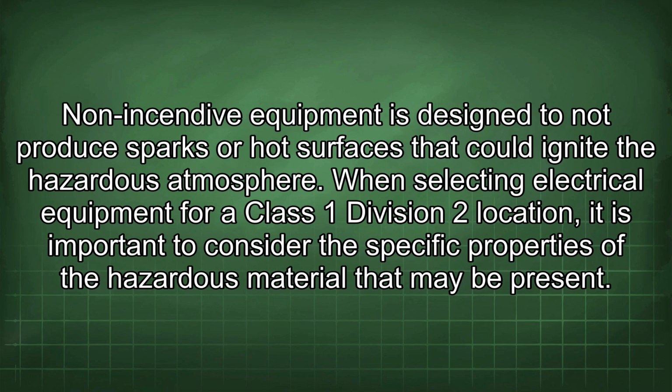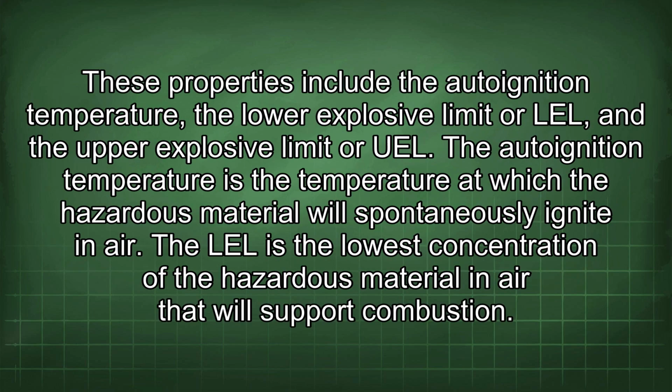Non-incendive equipment is designed to not produce sparks or hot surfaces that could ignite the hazardous atmosphere. When selecting electrical equipment for a Class 1 Division 2 location, it is important to consider the specific properties of the hazardous material that may be present. These properties include the auto-ignition temperature, the lower explosive limit or LEL, and the upper explosive limit or UEL.